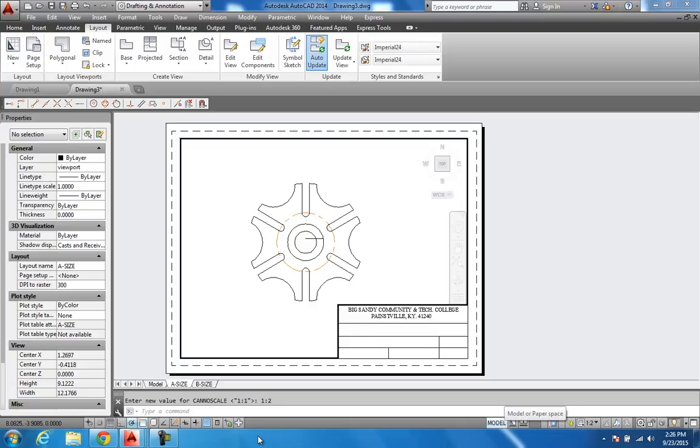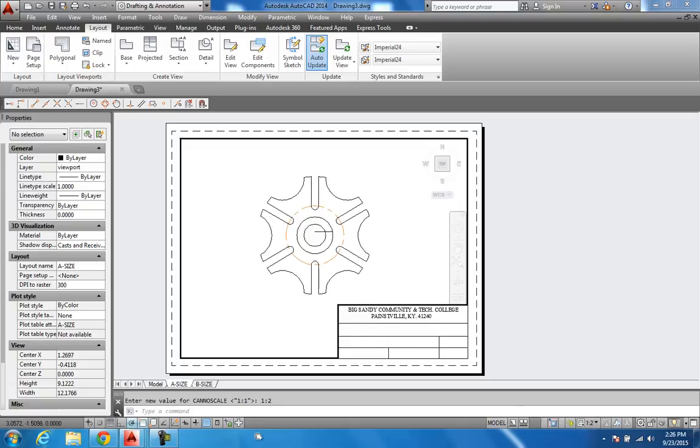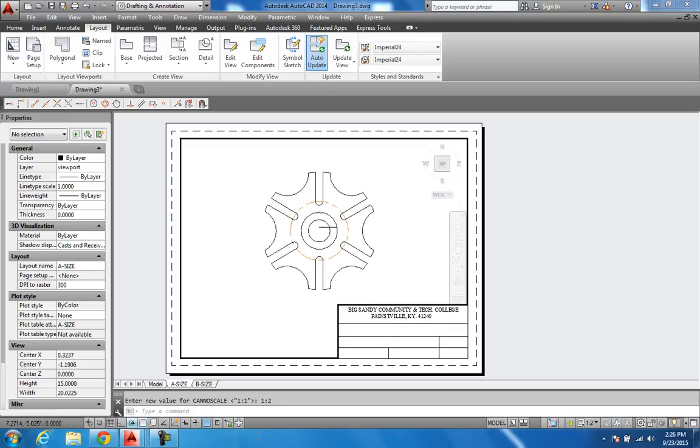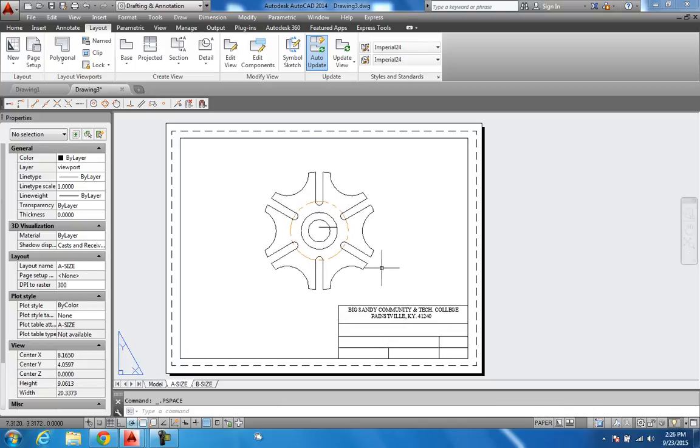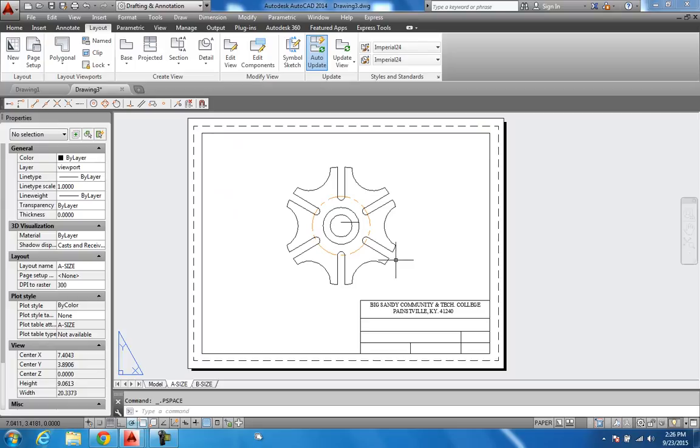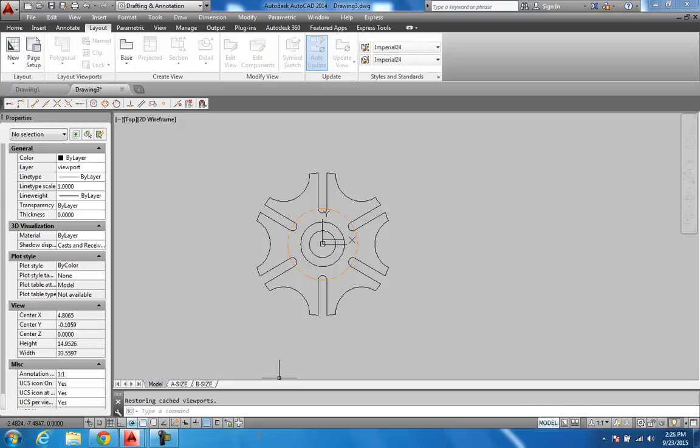And I'm going to switch it back after model space, get it to where you want it at, and I want to go back to paper space, and now it's stuck there. It looks great. That's a half scale. I want to go back over to my model, and I've got to change. You see this annotative scale? This is my annotations, like my text and multi-liters, dimensions. I want to change it to 1 to 2 so it matches my paper space scale.